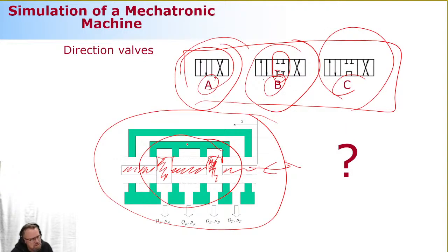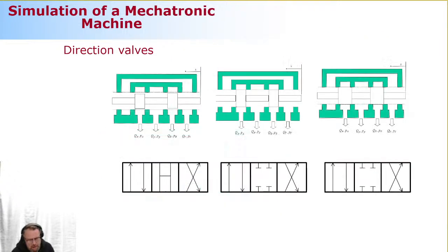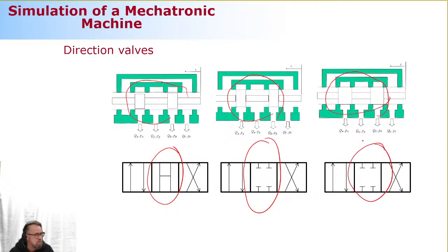So it's hard to calibrate your spool in a way that there's no flow whatsoever when you have this zero land system. And you can have even the minus land, like it is shown here. In the middle configuration, everything is connected, more or less. You can have this zero land, like the one we looked at a little while ago, or you can have the positive land. And the positive land has the same drawing symbol as a zero land. So no difference.